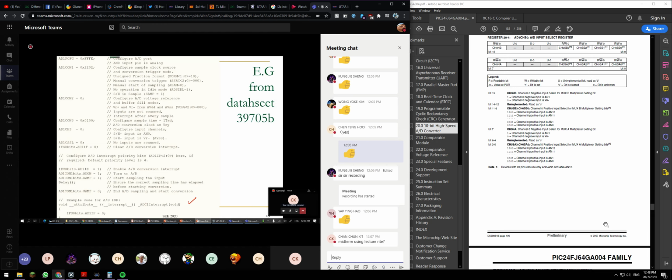These are the fixed reserved words, ADC interrupt. Here you can put no auto PSC, here is the same. So you just configure accordingly. When the interrupt occurs, you clear the interrupt, the analog digital converter interrupt flag, and perform. How you write the interrupt service routine is up to you.